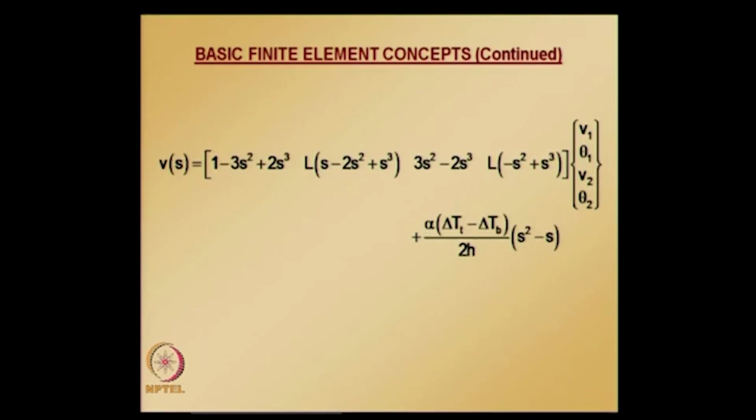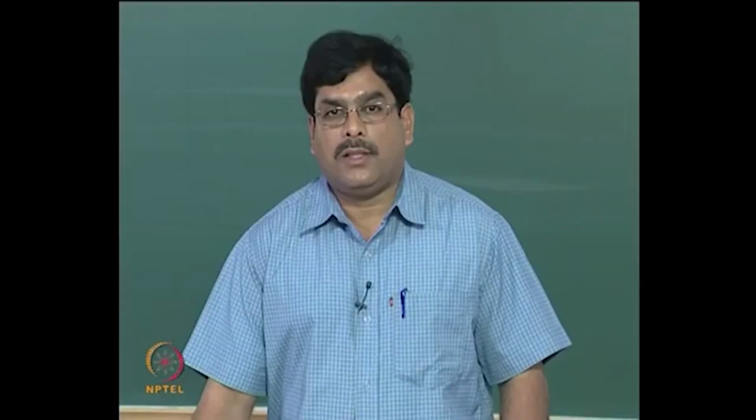Here the fixed end solution is nothing but the beam trying to undergo some curvature because of the temperature difference of the top surface and bottom surface, and it is restrained, and so we know how to calculate curvature and also moment.